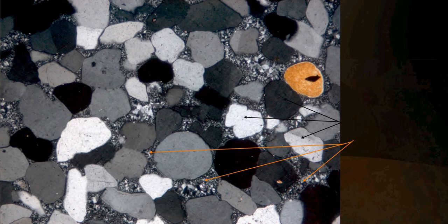Quartzite. This is a thin section under the microscope showing quartzite, how quartzite occurs. This is, by the way, orthoquartzite. In fact, orthoquartzite is a kind of sandstone. The difference between sandstone and quartzite is that the bonding is much stronger, and the binding material which binds the quartz grains together in quartzite is silica. It is siliceous binding material.